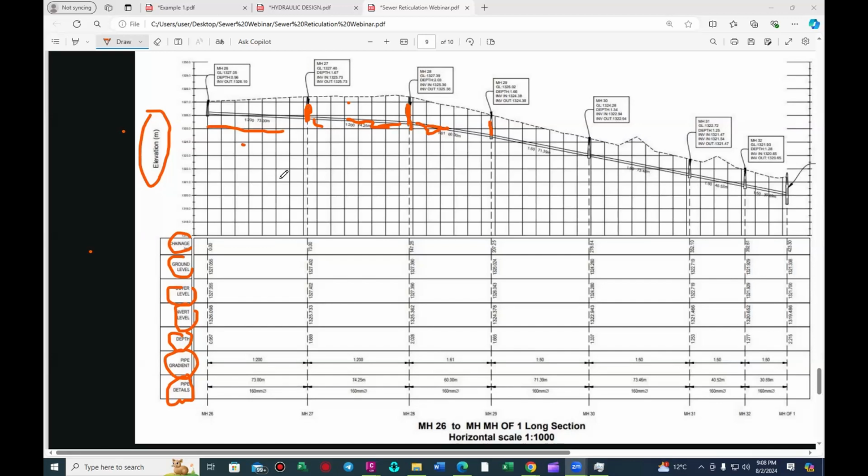Also try and make sure that your sanitary sewer system does not follow the terrain of the lowest possible area, because in lowest possible areas, there tends to be a lot of ponding when it rains. So when it rains and there's ponding and there's a manhole there, water will naturally trickle into your manhole and act as a catch basin, right?